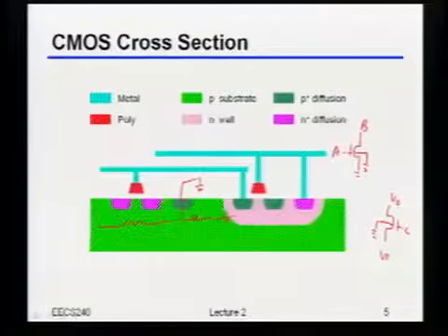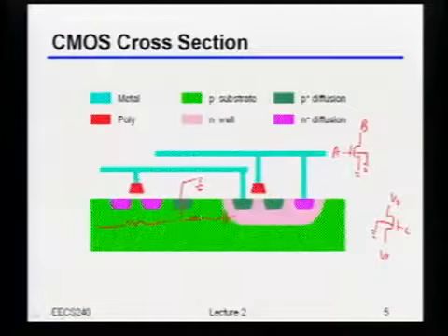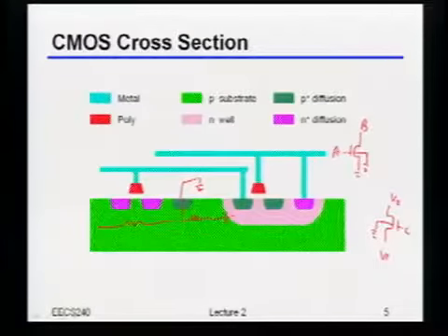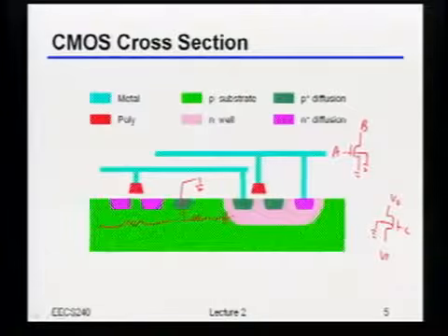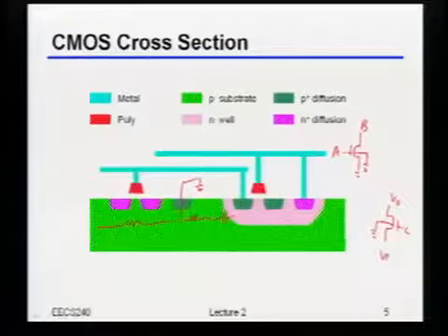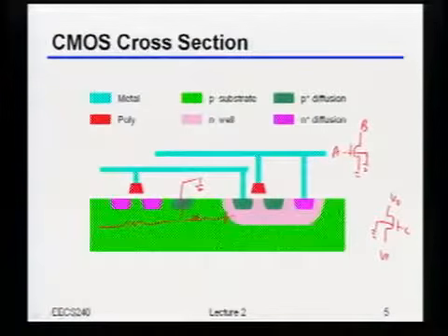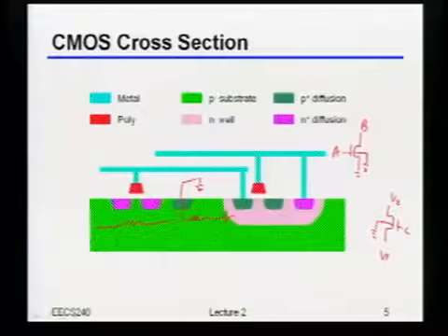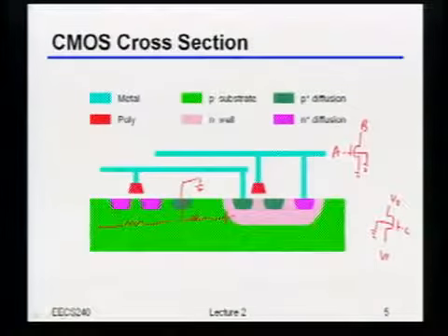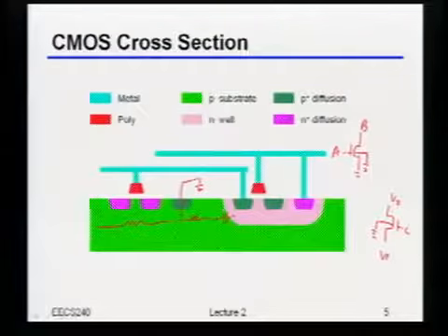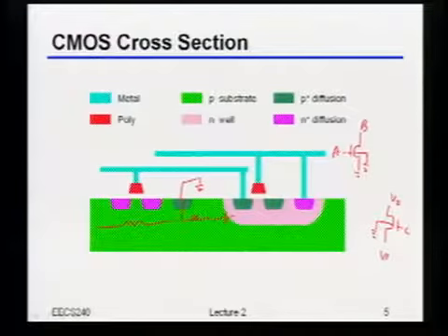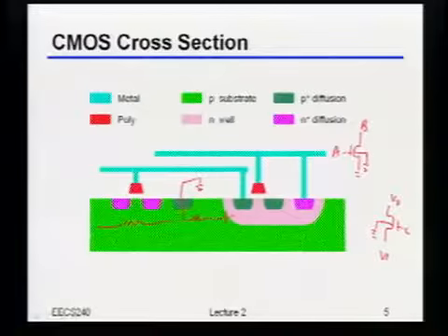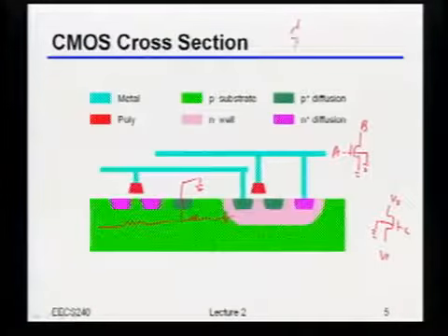Specifically with PMOSs in like a single well process. What do I have to do to build a PMOS transistor? It's like the first thing I have to put. Use an N-well? Yeah, I have to put an N-well. So, anybody know of another name for an N-well sitting inside of a P substrate? It's a circuit element that, Diode. It's a diode, right?